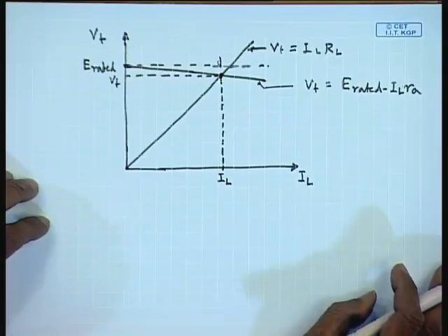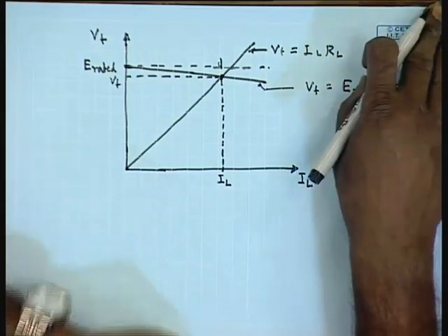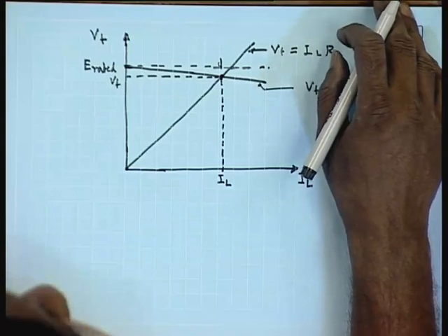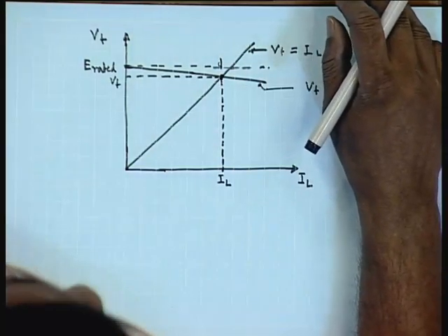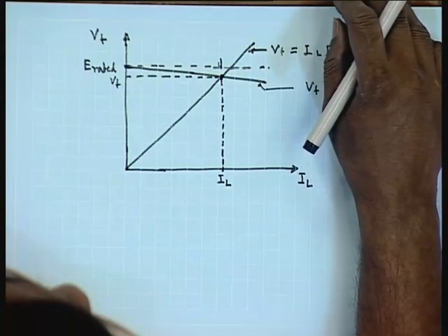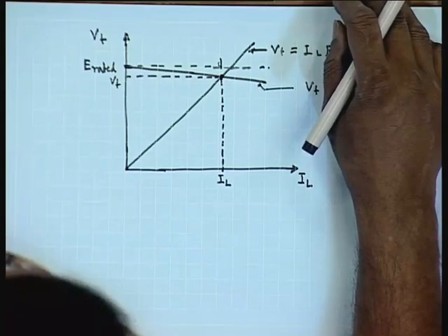We have seen before that due to current flowing in the armature, the field flux is distorted; the field flux at one half of the pole tip increases and in the other half it decreases.